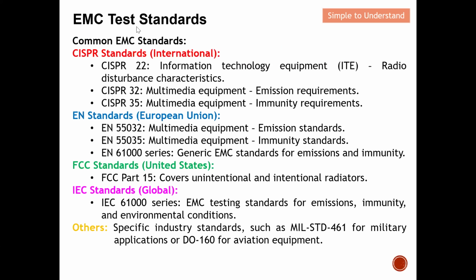These are the common EMC test standards. The CISPR standard is an international standard. We have CISPR 22, CISPR 32, and CISPR 35. You can see that they target different test devices. CISPR 22 is mainly for information technology equipment, IT, with some emission requirements in order for them to work. CISPR 32 and 35 cover the emission and also the immunity for multimedia equipment. Nowadays we are going to have more and more of this multimedia equipment.